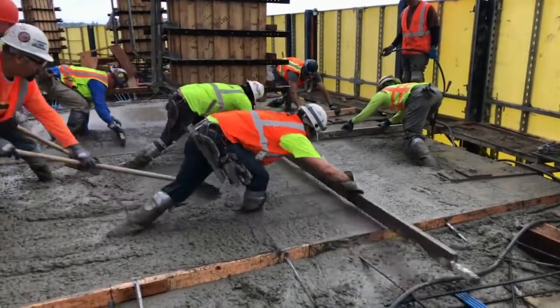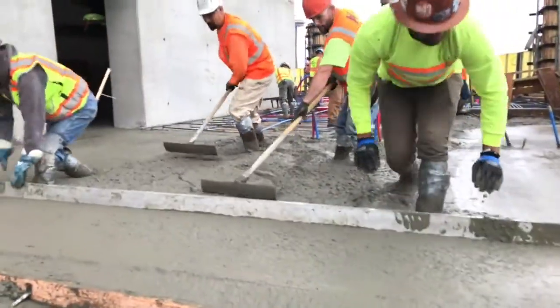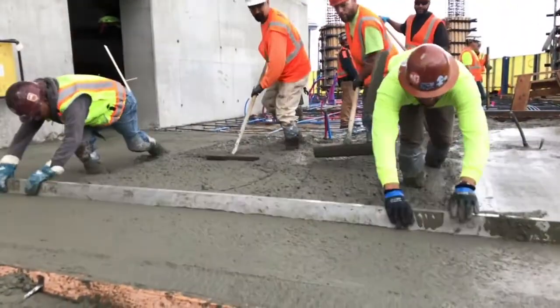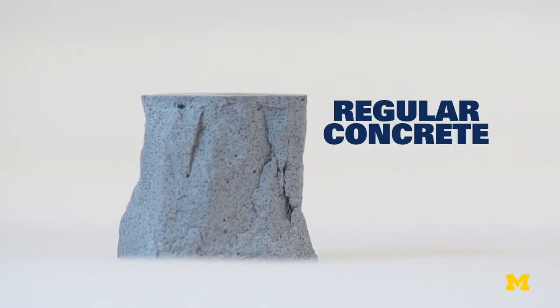There were many design challenges faced when creating the column design, the first of which was choosing appropriate loads for a residential apartment, as floor, wall and slab loads had to be found using the Australian standards. After finding the dead and live loads, we were required to calculate appropriate tributary areas and therefore find appropriate uniformly distributed loads. From this, we were then required to find a material with a large enough cross-section to be able to withstand the compressive forces required.